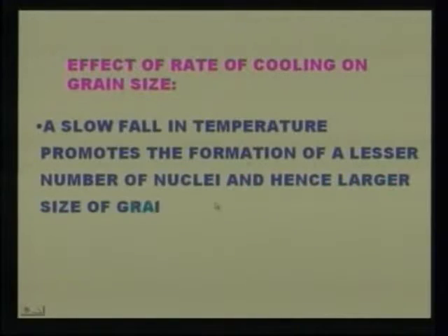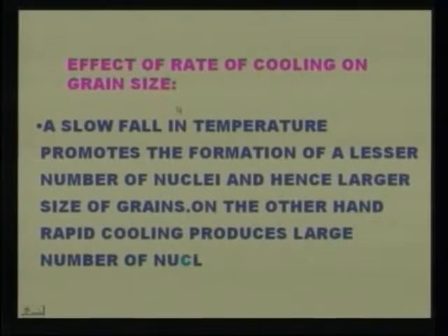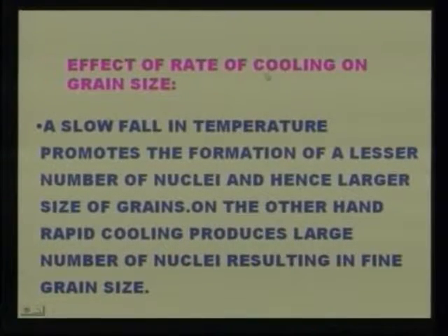Now let us see the effect of the rate of cooling on grain size. What is the effect of cooling? A slow fall in temperature promotes the formation of a lesser number of nuclei and hence a larger size of grains. On the other hand, rapid cooling produces a larger number of nuclei, resulting in fine grain size.